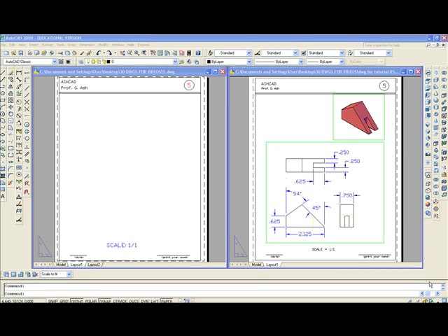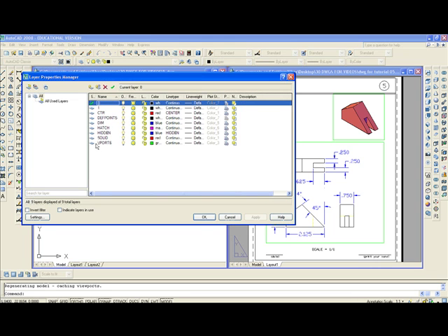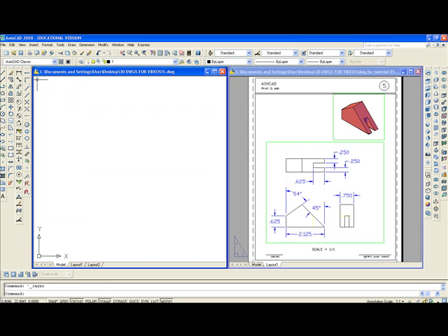This is going to be exercise number 5. First thing I'll do is click on Model button. Then what you have to do is go to Layer, make Layer 1 Current, and then start to draw.